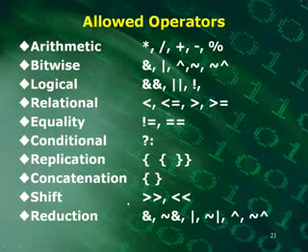Okay, that's what I was wondering. Yeah, ModelSim doesn't care whether you're doing the full functional Verilog or just the subset. It doesn't know what you're up to. But when you go to synthesis with your vendor tools, whether it be Altera or Xilinx or whoever, then you're going to know whether it's synthesizable or not. You're going to get warnings.